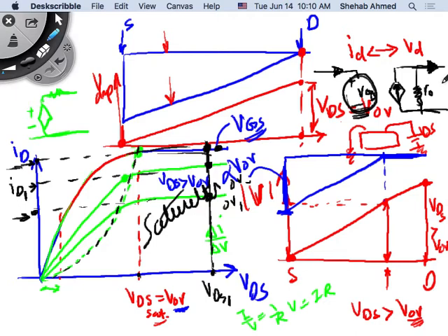Remember those models from chapter 1? We had ones that are voltage input, voltage output; voltage input, current output; current input, current output. So this is a voltage input, current output type model with an infinite output impedance in parallel with the current source, which means it does not affect the value of the current. This is all ideal, okay?